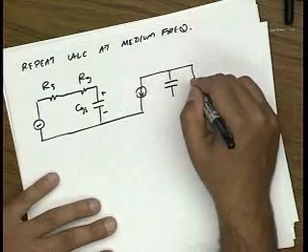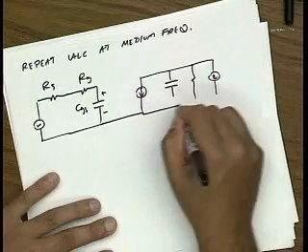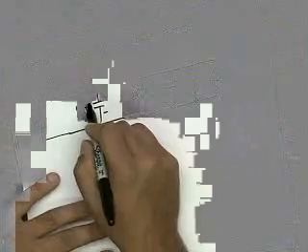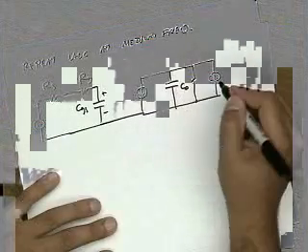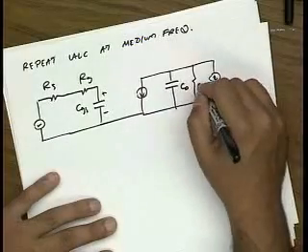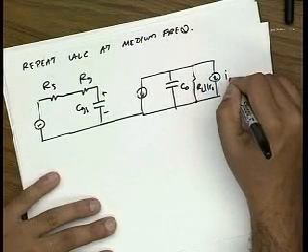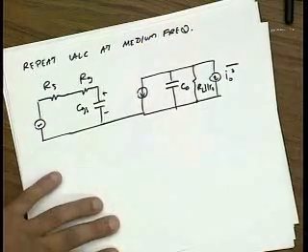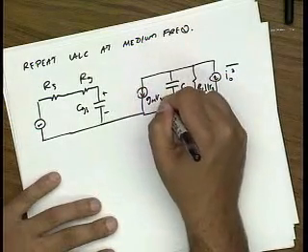If you're really eager to include it, you can basically use the Miller effect and add a capacitance and make CGS artificially larger and C out slightly larger. So this is C out. This is RL in parallel with RO. This is the noise due to RL. Let's just call this the total output noise, which includes the drain noise and RO. And this is GM VGS.